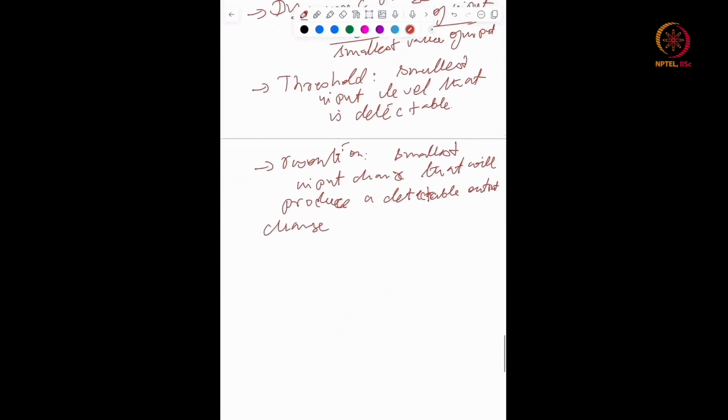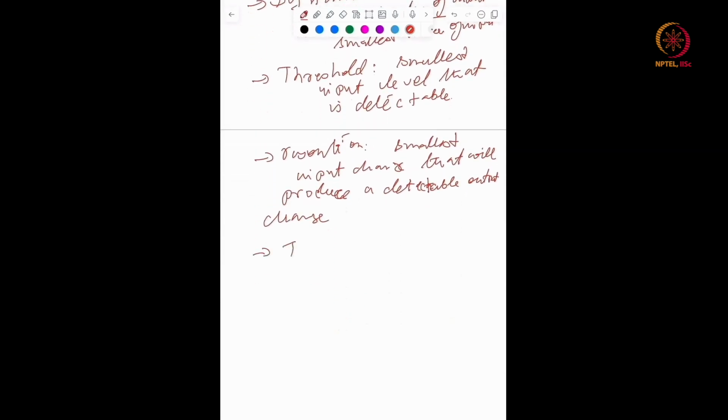There can also be features like hysteresis. The hysteresis is the difference between the output value corresponding to an input value, the output value that was reached while you are going up versus going down, reached from below and reached from above. So if you go from point 1 to point 2, and then come back like that, that is something like hysteresis. So up or down.